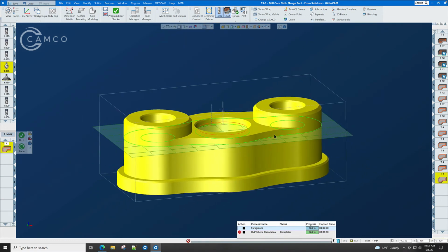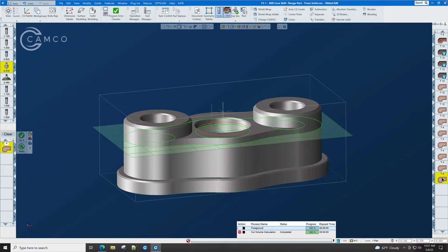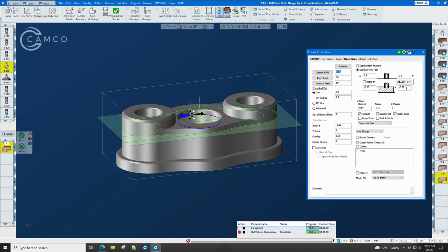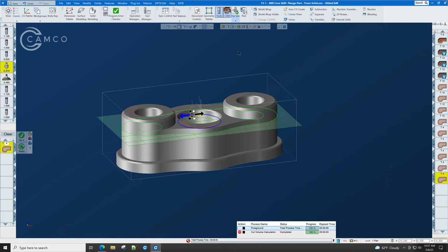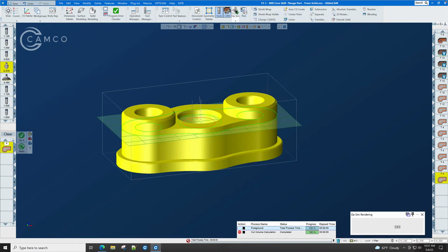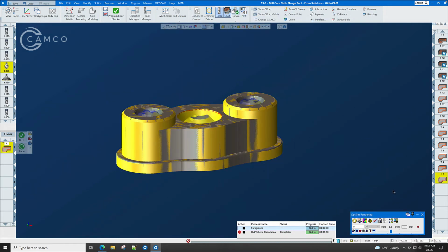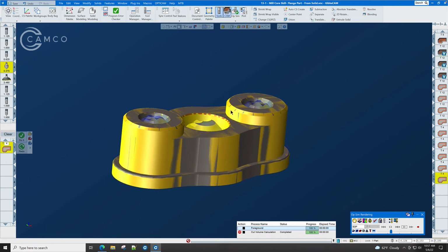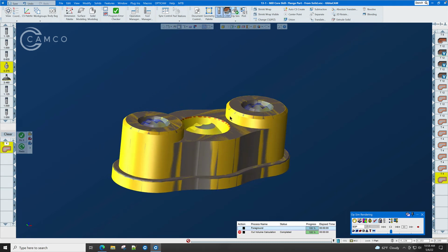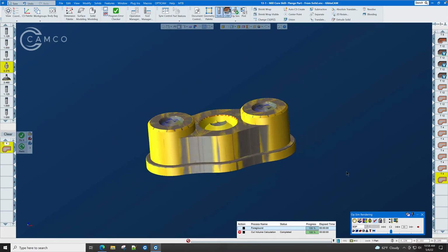How can we fix that? We're going to fix that by driving the cutter farther down in the part. Right now, we did a minus 250, minus 70 thousandths. How about minus 0.250, minus 0.150 equals? And then press redo. Now that we've done a redo here, let's go to select the part and to OpSim and click the Do It button. And now we are no longer cutting the edge of either one of these bosses.